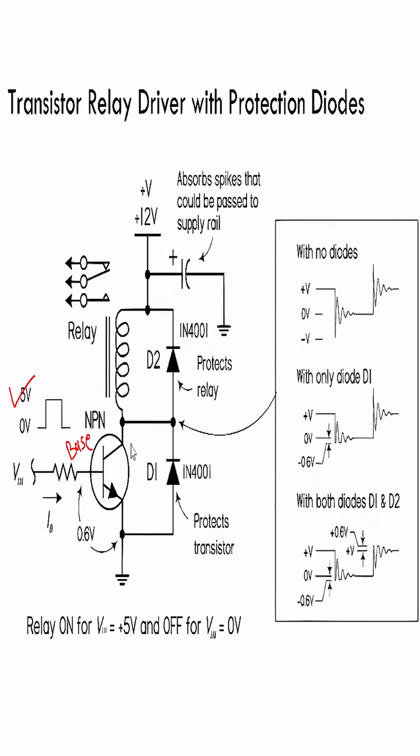the circuit is completed by the collector and emitter. So there is a collector and emitter, and this is a relay, and the whole arrangement is based on the relay. If someone is providing the power here, the current will flow from positive to the collector, then emitter, then ground. So there is a requirement of ground here. How will the ground be received? When the base current is provided, this circuit will be completed, the ground will come from here to here, and the relay will start working.